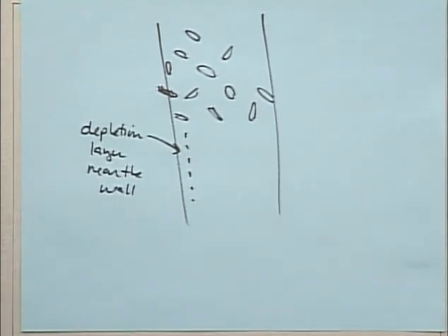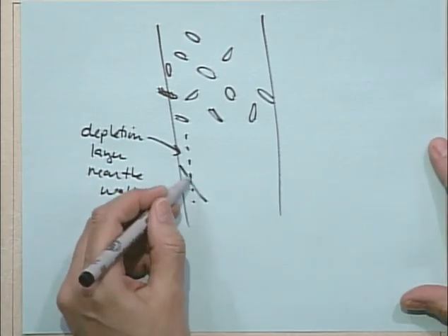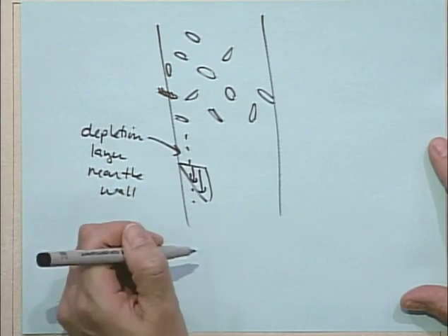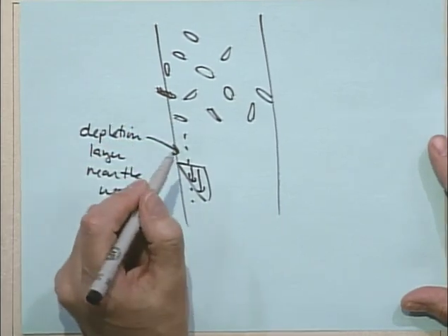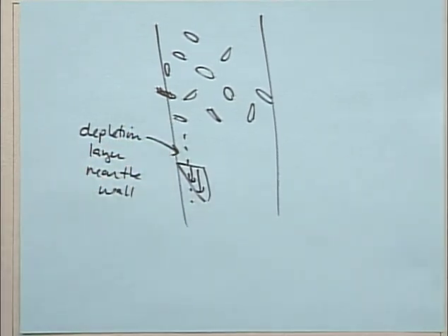And so all of our formulas are messed up, because all of our formulas are based on what the shear flow is like near the wall, and if there are wall effects, it's going to mess up our calculation. So that's something always to keep in the back of your mind when you're dealing with inhomogeneous material. It has fewer particles. So if you imagine marbles bouncing around, they propagate all throughout the space, but when they get near the wall, they can't propagate through the wall. So they're pushed away. They stay away from the wall, exactly.